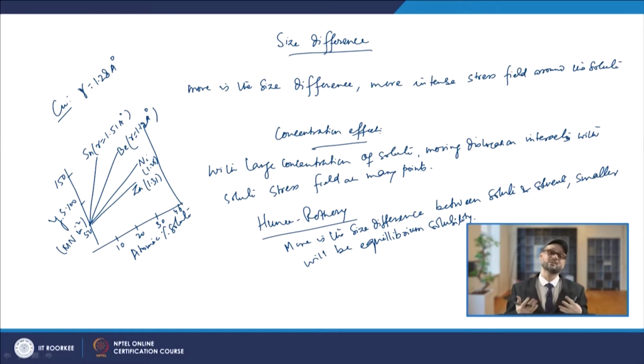So the solubility increases about 40 times when you increase the temperature, and then you cool it rapidly. Basically an intense stress field is generated, and it interacts with dislocation movement. That way you have an effective hindrance to the movement of dislocations, and you achieve the strengthening effect in the case of steel.